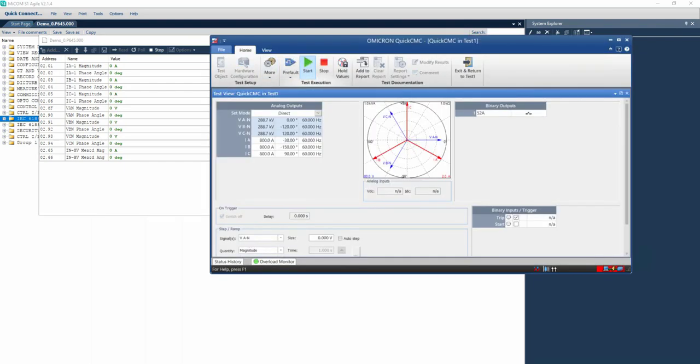So I'm going to inject these voltage signals, and as you can see here, they show up here. As we said, VA, the voltage of phase A to neutral, is going to be our reference. That's where you see the 0 degree here. So that's it for now. Then we'll head to the configuration of the CMC to stream GOOSE messages.